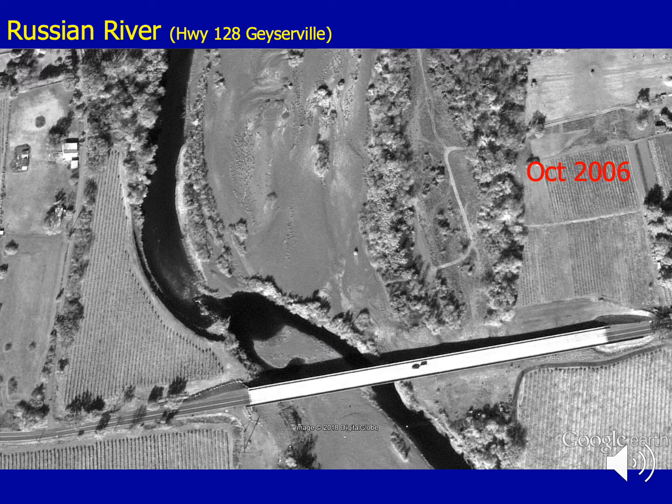When those piers are oriented in the direction of the bridge, they essentially act like bedload transport vanes. So think of it as the airflow vanes in the AC in your car. When you move those things back and forth, it redirects the air. The piers sort of act the same way. They're controlling the trajectory of bedload transport and scour here. So we're pretty much always going to scour and transport this direction. So this river that used to formerly flop back and forth within its floodplain here is pretty much always going to have an axis that looks like this. This leads to increased bank erosion on the outside bend here.